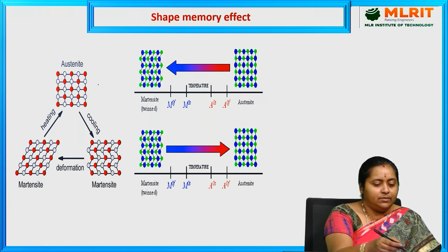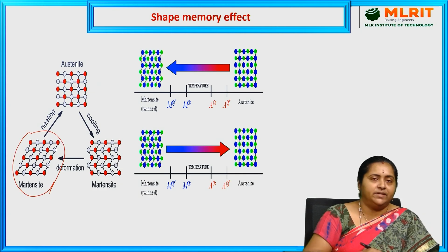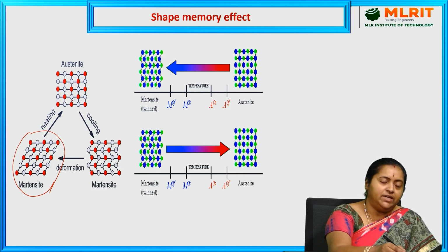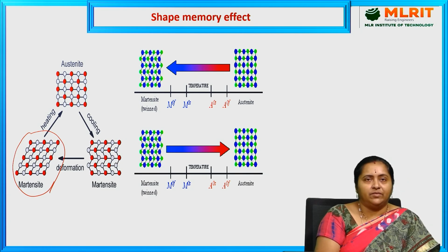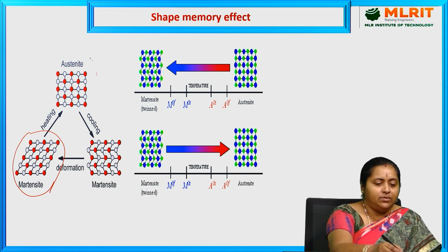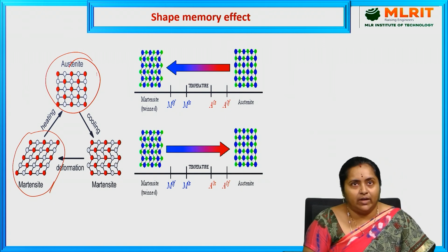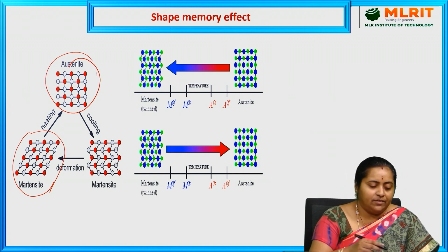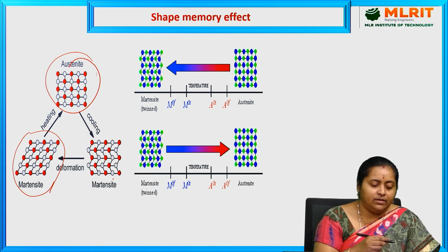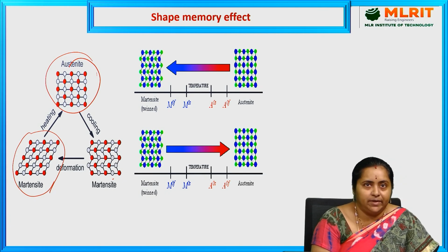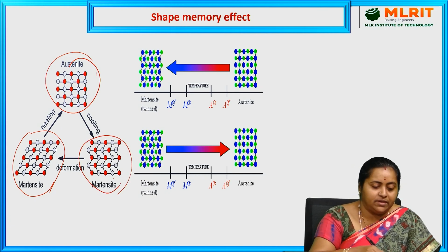That is martensite. Actually it has this kind of shape and size, and when subjected to heating by supplying some amount of temperature, it is able to convert into austenite. A proper alignment we can notice in the alloy's solid form. After cooling, it will change its shape. That is also known as martensite while cooling.